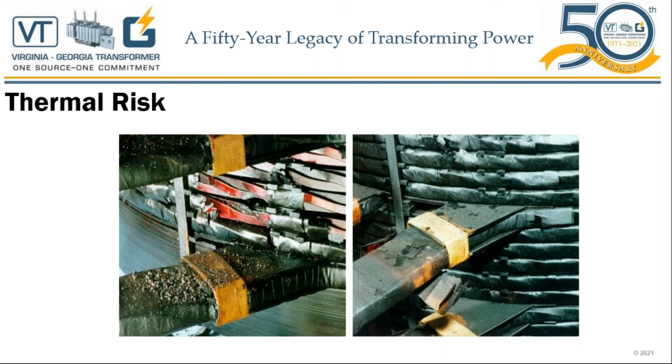And of course, as our insulation integrity reduces, then the strength against dielectric forces, which we will discuss, reduces. So even a simple transient voltage or a lightning event will cause this transformer to have a dielectric failure, but the true cause behind everything could be that the insulation has aged due to thermal stresses over the years and just could not handle the dielectric strength anymore.